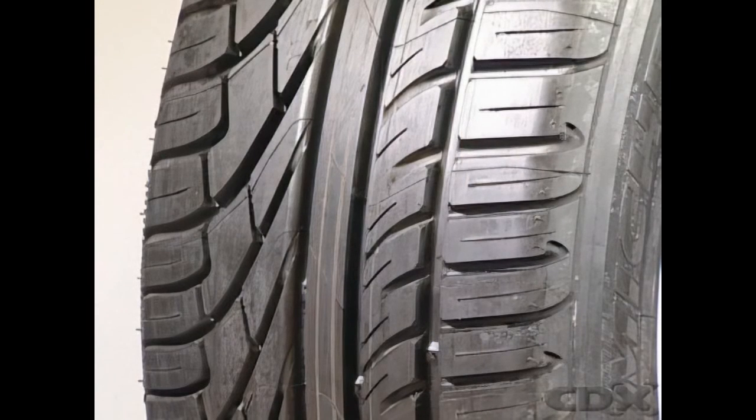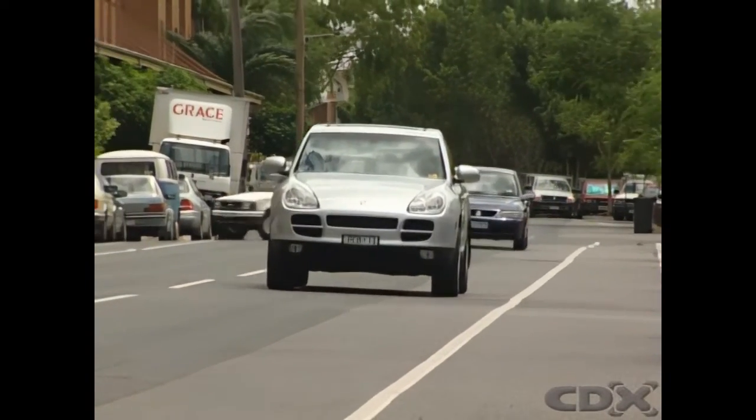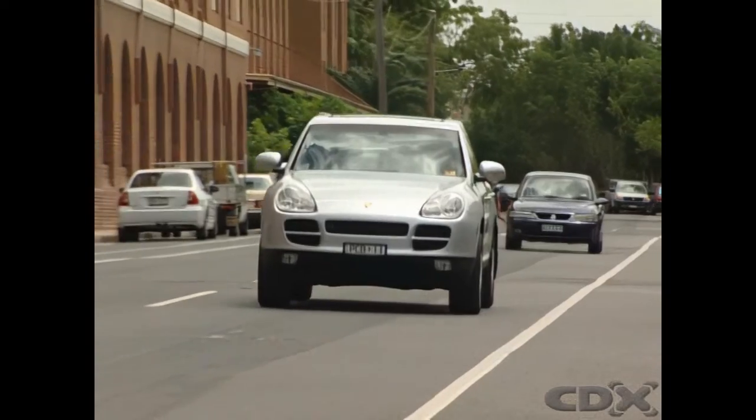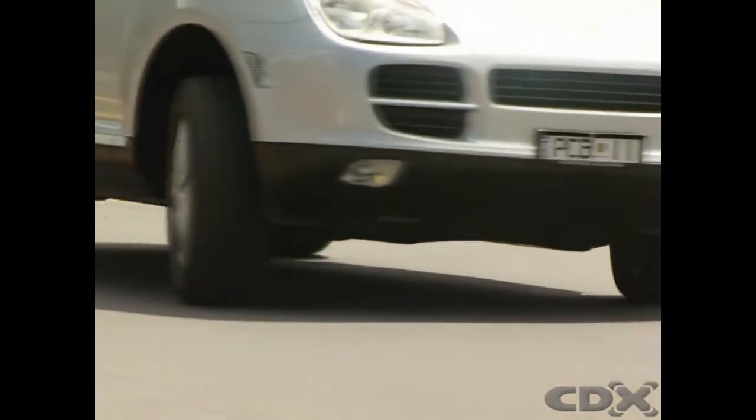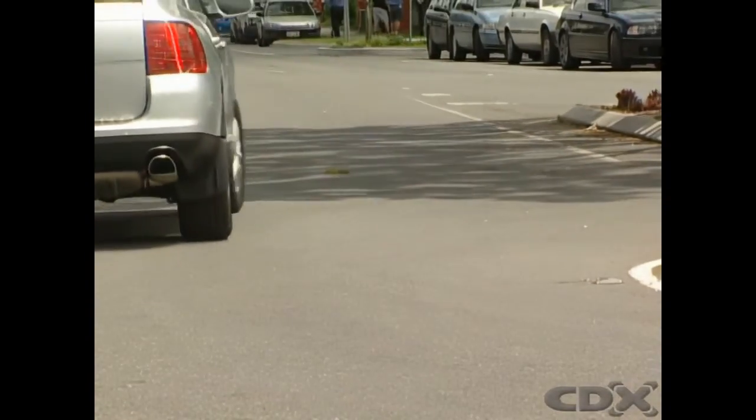Asymmetric tread patterns have a tread pattern that is different from one side of the tire to the other. They are designed to provide good grip when traveling straight and in turns. They are generally directional tires and must be fitted to the road wheel in accordance with the fitting instructions to ensure that they perform as designed under operating conditions.